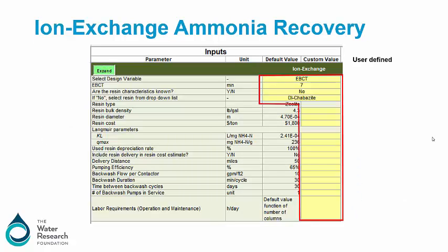Design parameters include sizing columns based on empty bed contact time, EBCT, or days to breakthrough, defining the resin characteristics or selecting from a list of reference resins, specifying delivery distance, pumping efficiency, and backwash requirements.